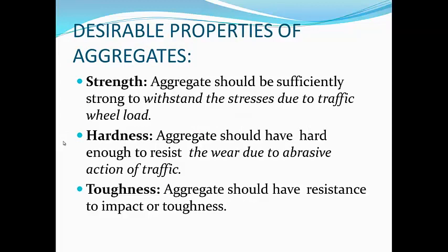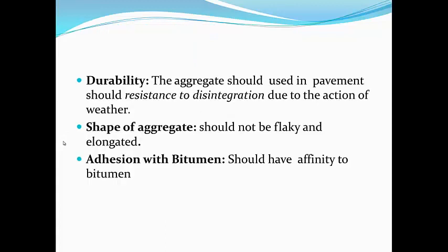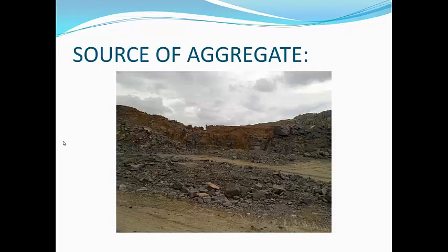And coming to the aggregates, the strength of the aggregates mainly depends upon the properties of the aggregates, and such properties that are to be tested are strength, hardness, toughness, durability, shape of the aggregate, and also the adhesion with the bitumen.